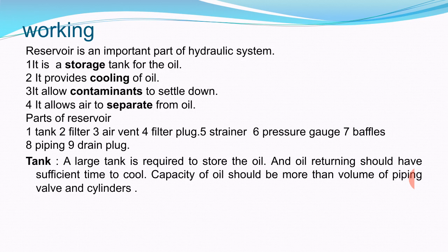Now the tank: a large tank is required to store the oil, and the returning oil should have sufficient time to cool. So the capacity of oil should be more than the volume of piping, valves and cylinder. There should be excess oil in the reservoir, meaning it should be more than what is needed after filling the pipeline, valves and actuators.